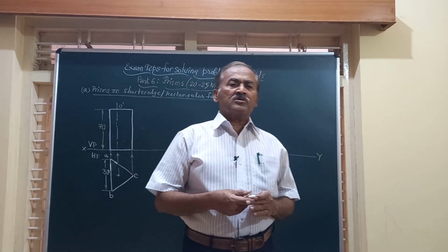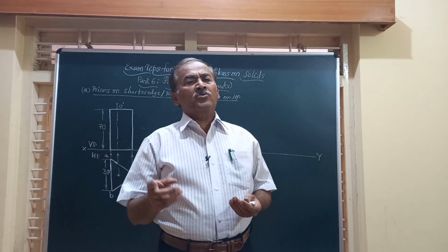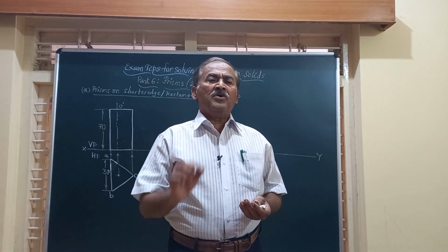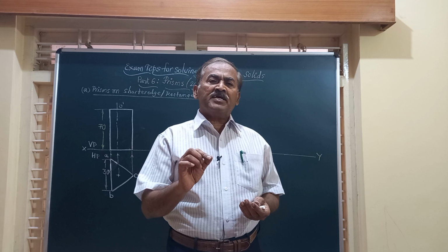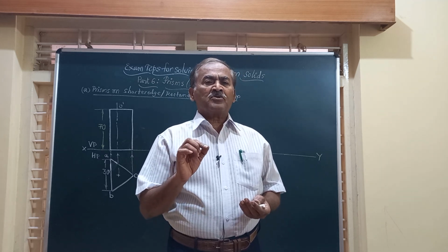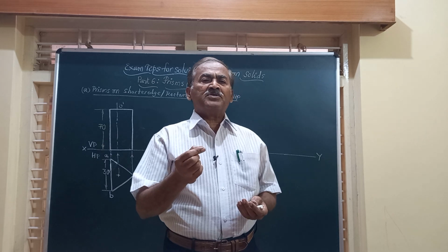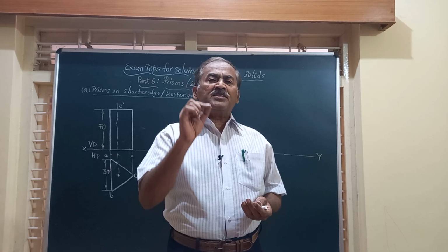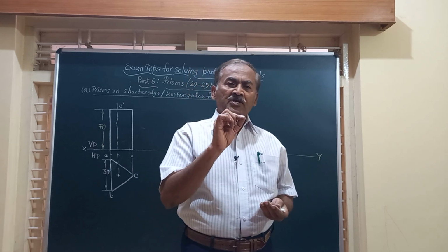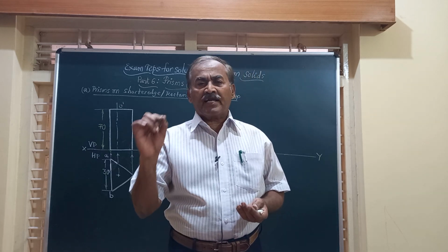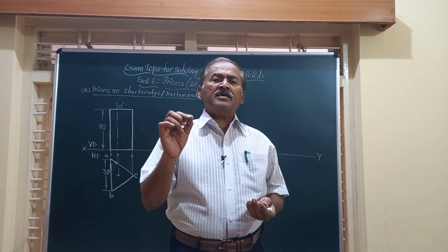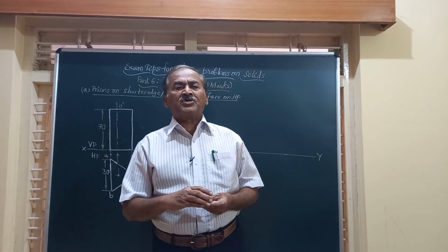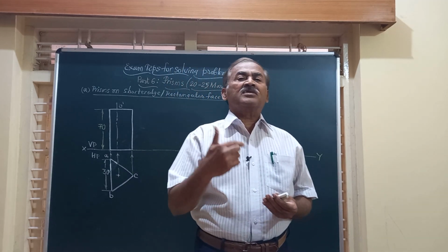Friends, generally it involves three steps. And out of these three steps, the first step is very, very important, wherein we are going to place the object on HP usually. After placing the object in the correct position with reference to HP and VP, we obtain the top view and front view. And if you are able to complete the first step correctly, very systematically and in a very simple way, you will not have any difficulty to obtain the projections in the second stage.